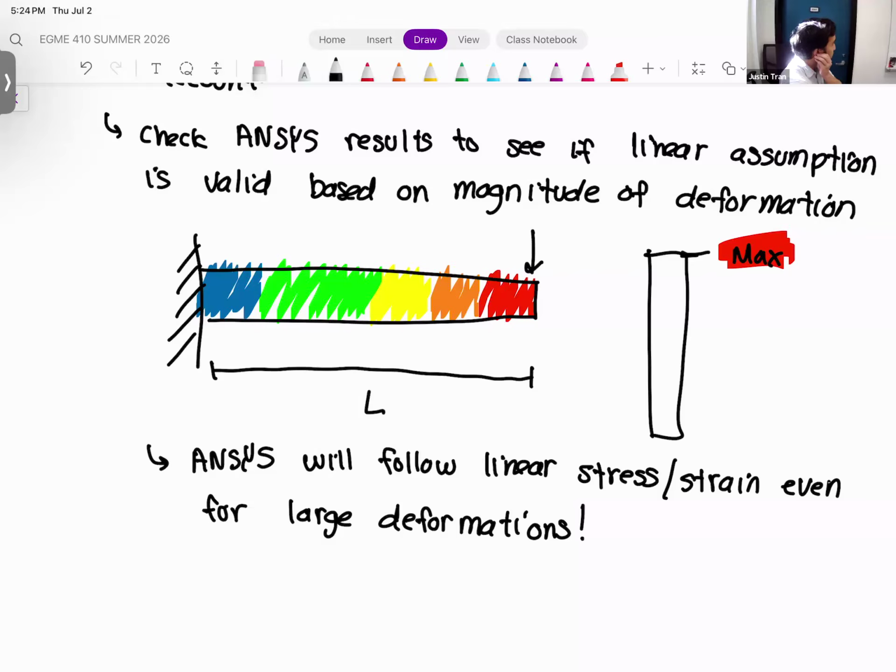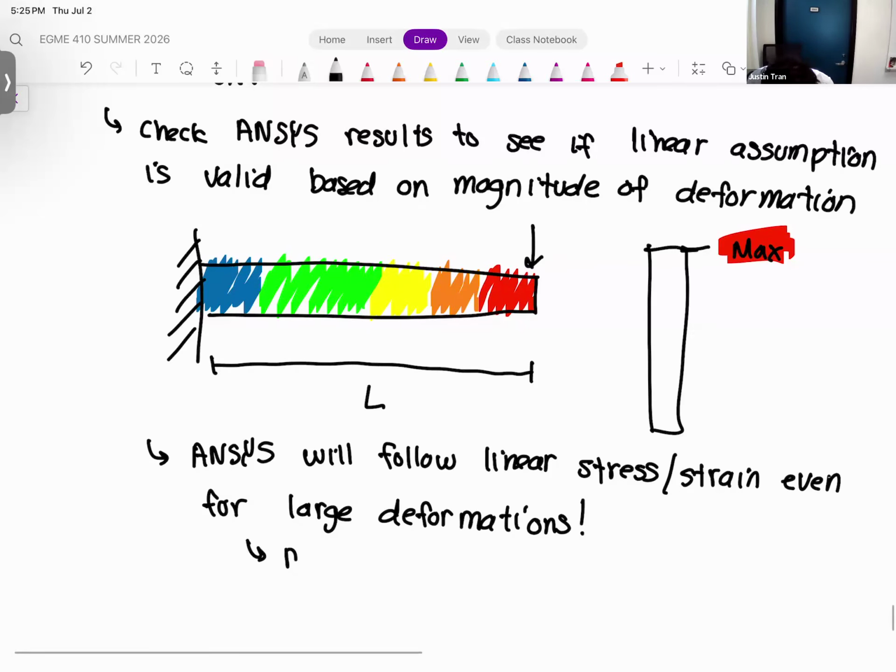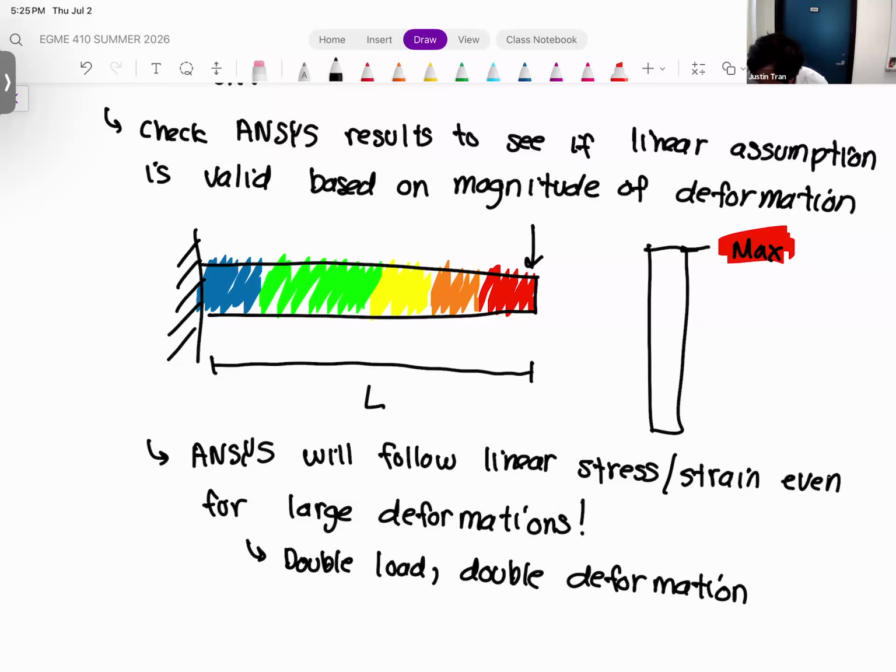And so you'll see this in activity too, right? So what linear basically means is that, as you increase the loading, the amount of deformation is going to increase proportionally. Okay. So if you double the amount of force that you're applying onto a structure, then your deformation is also going to double as well, right? That's what the linear relationship means. Same thing if you triple it. Okay.